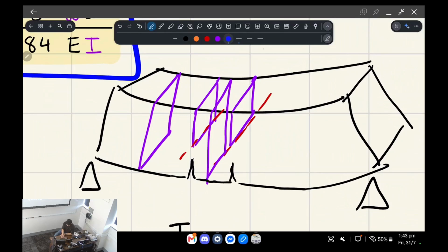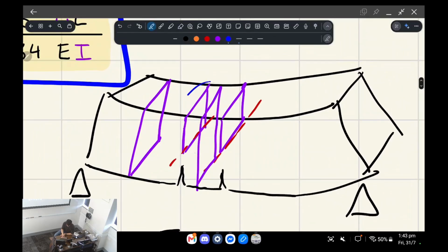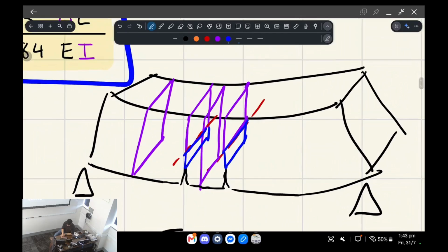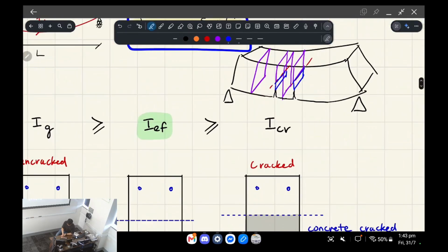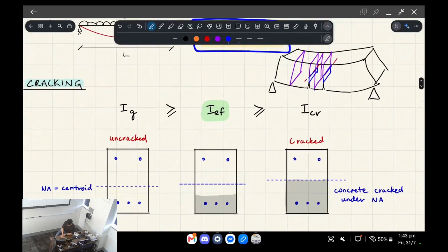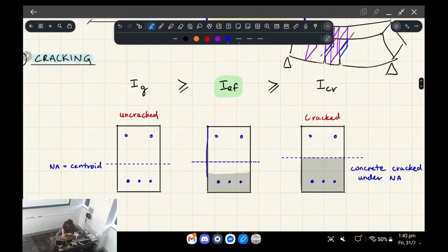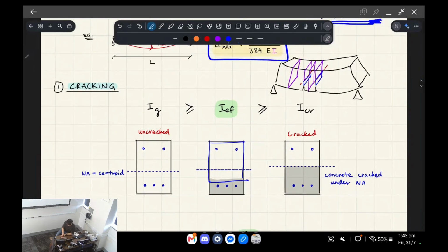Conservatively, we took everything below the neutral axis as being in tension and not working, but even some bits in tension can contribute to the stiffness, for the case between stage 1 and 2 for the reinforced concrete. That's basically what this is, saying that not everything below the neutral axis is ineffective.